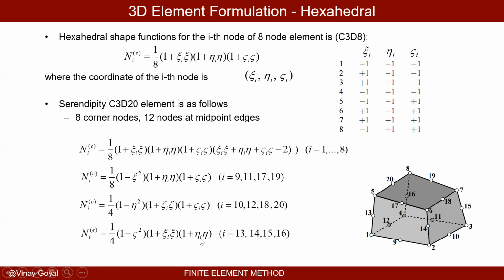But the bottom line is that you do have 20 shape functions because you have 20 nodes. And notice how at each node there are three unknowns, the deflections in three different directions. Bottom line is once you have these shape functions, they're the same for every element.